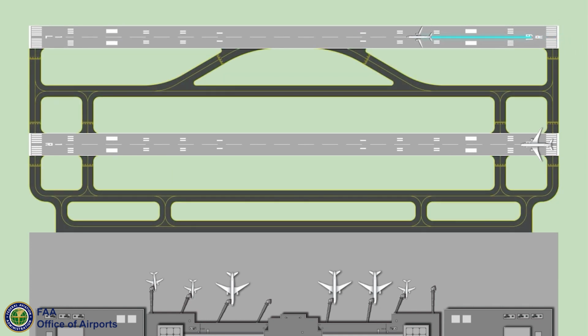Proper, long-term airfield planning and design provides sufficient separation distance between runways for a parallel taxiway, eliminating direct runway access from the high-speed exit.